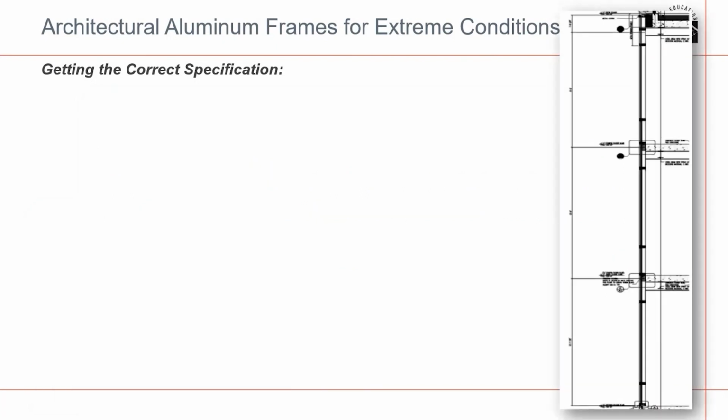While we're talking about sound, let's look at another point here. This is a section cut through a typical curtain wall. We've taken great steps now to try to stop sound entering from the interior. But on some projects, such as high-rise multifamily projects, you're also concerned about sound within the building passing one floor to the next. Sound can travel through mullions, past floor lines, and move from one floor to the next.